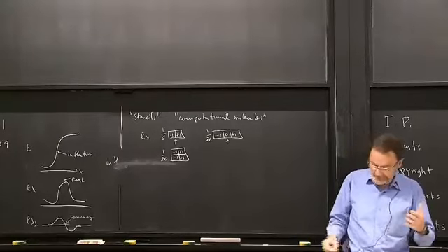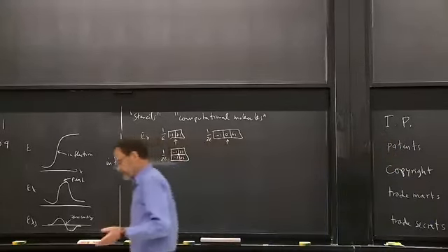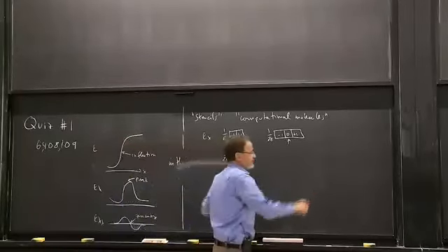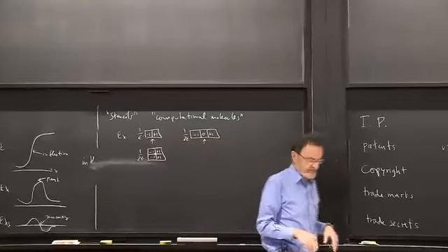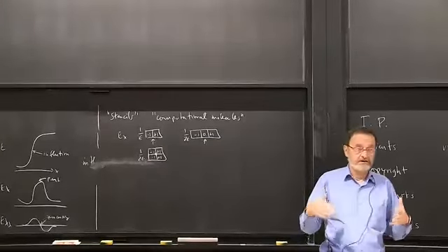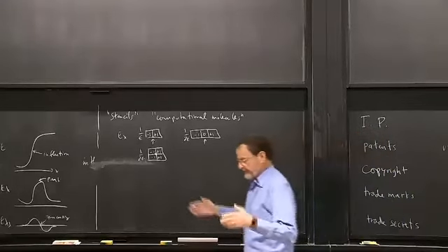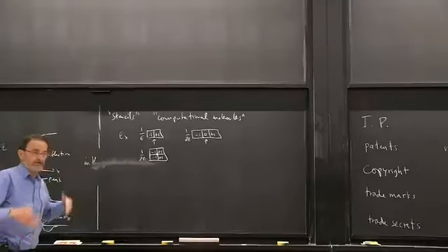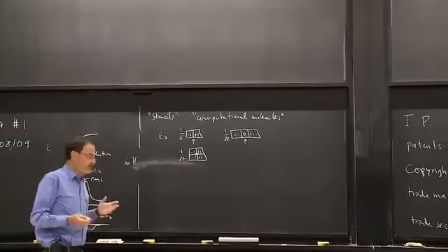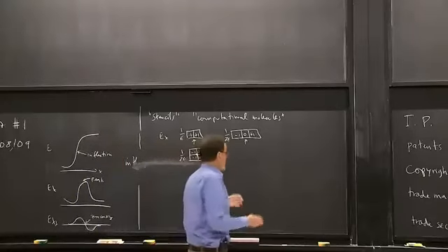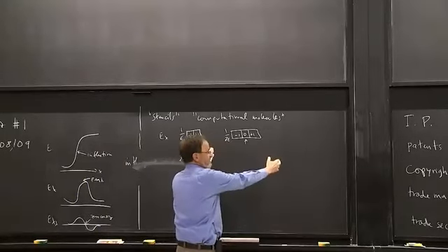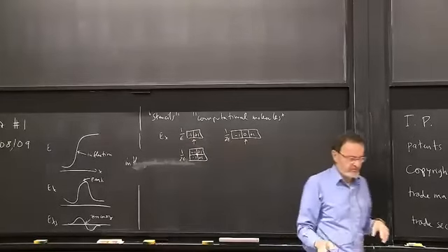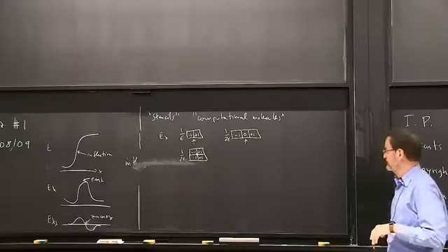So we're using very low order, partly because it's easier, and partly because one other trade-off is if you make them too long, then they start to have different features interacting with each other. Here we're trying to detect an edge. Now if you use an edge operator that's 100 pixels long, and there's another edge within that 100 pixels, it's going to interfere with the result. So we try to compromise. On the one hand, we get better results with bigger support, better noise suppression, but at the same time, we run more into the problem of what happens when two edges get close to each other.